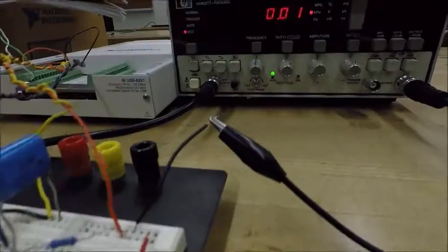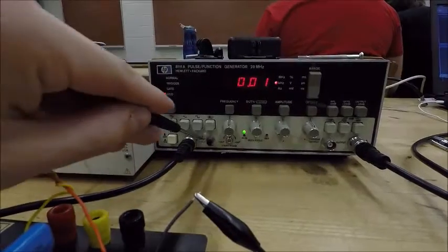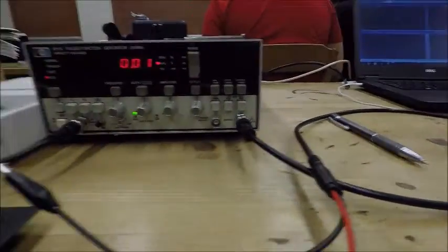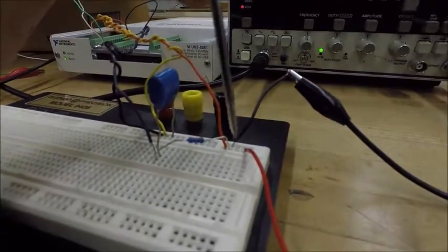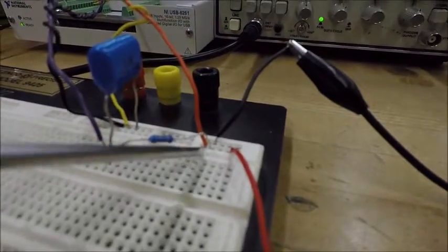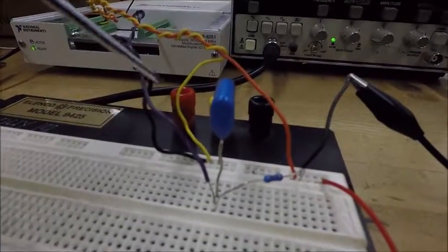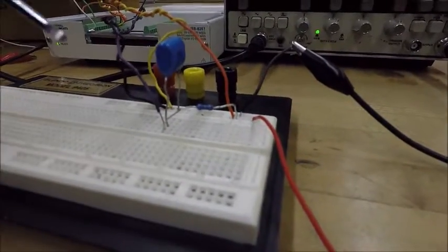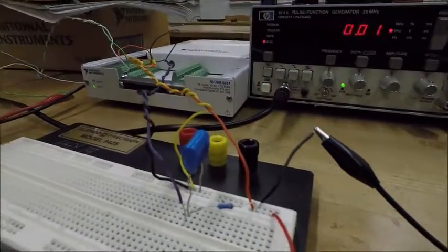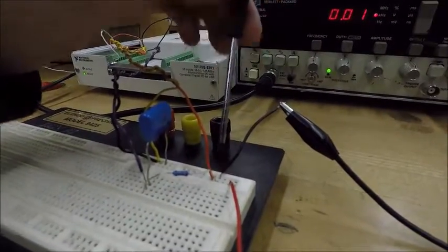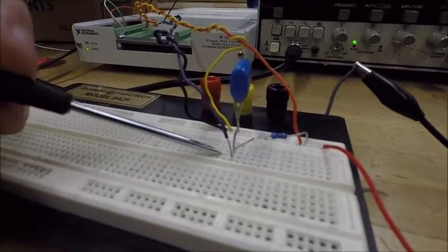Here we have our circuit, and how we have this set up is our DAC is controlling our function generator through the external input. We then get an output from our function generator that runs to our breadboard through a positive and our ground, and then our power goes into a 1 kilo ohm resistor, which then goes to a 1 microfarad capacitor and then back to ground. What's very important is what's in between those two components. What we're measuring with our orange wire, hooked up through our DAC, is our V in, and then between the resistor and the capacitor, the purple wire, also hooked up to our DAC, is measuring our V out.